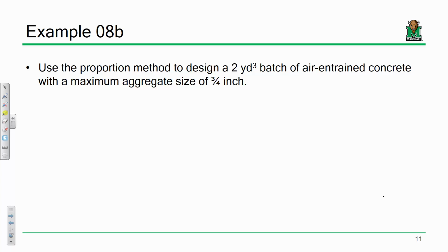We tend to go with water and cement first because those are our cementitious materials, where a chemical reaction comes from, and most of our strength comes from coarse aggregate. Now, the way that we determine the amount of fine aggregate is not from a weight proportion method, it's from a volume proportion method. So we'll say, all right, we know how much water, cement, and coarse aggregate needs to go into it. We'll take each of those quantities, determine how much volume that takes up. Then we'll say, how much additional sand will need to go in there to get 1 cubic yard. Make sense? Be clear, these are really simple methods, though. But you are exactly right.